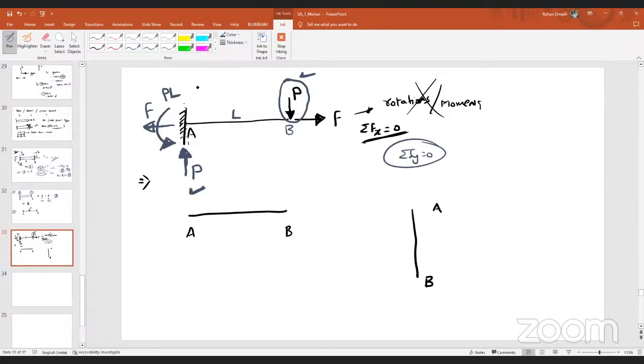So from this we can observe that because of axial forces, moments will not generate on the element. It doesn't matter what the orientation of the element is. If axial forces are acting on the element, they will not cause any moment. If vertical forces or shear forces are acting on the element, rotations may develop. To avoid those rotations, resisting moments should develop.